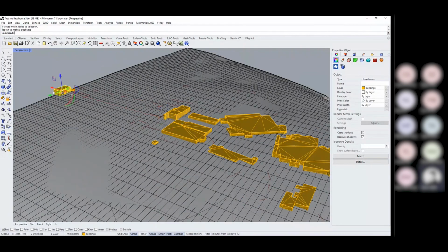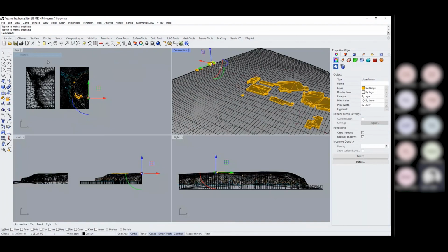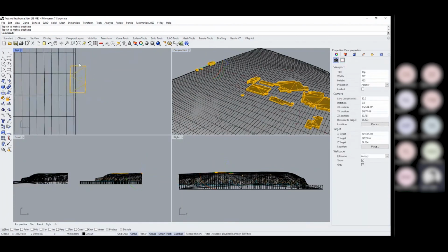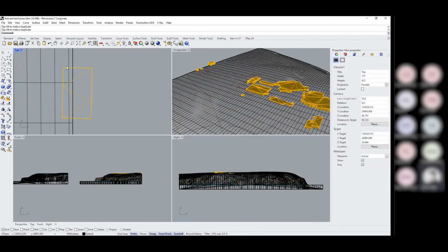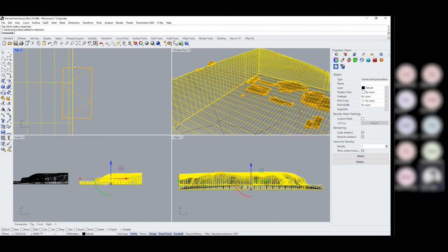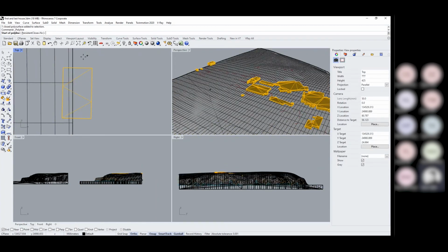Annoyingly, they're all perfect, which is typical. But let's say I had a mesh that sits on the edge, another way to trim this down. I don't want to 3D print it over the edge. Then what I'd probably want to do is just make something to cut it against. So I'm just going to make a little line across there to use as a cutting line. So this bit just there.